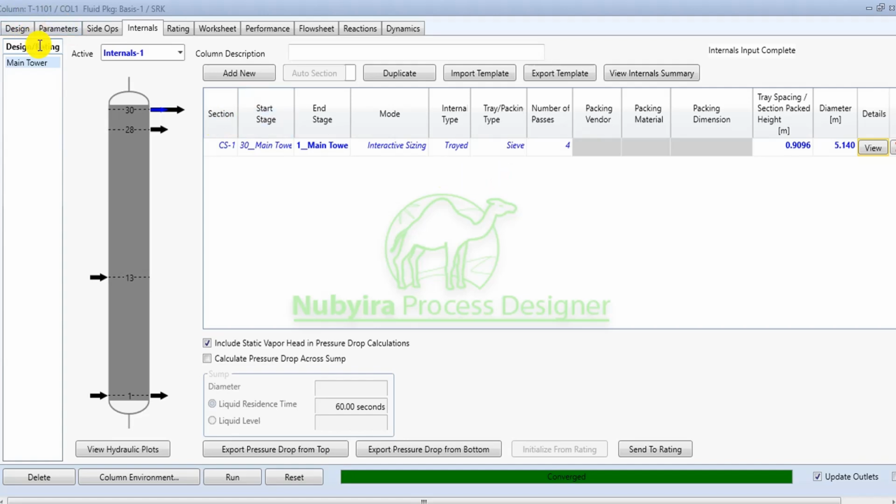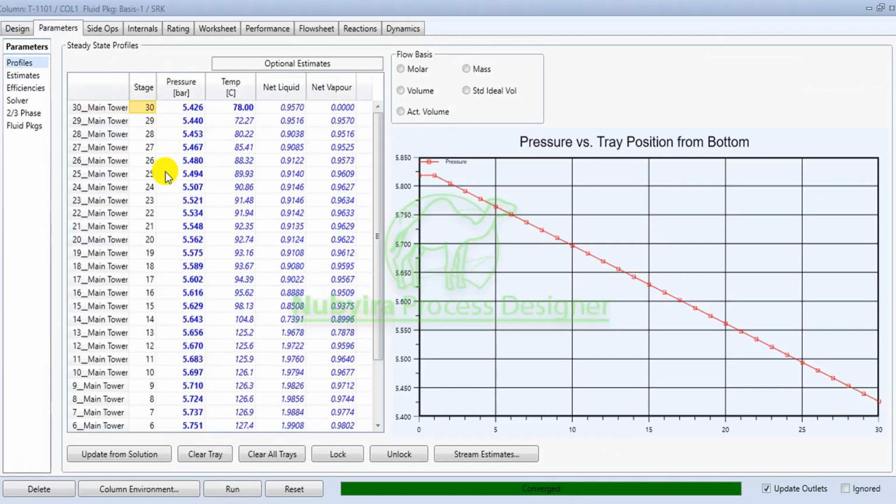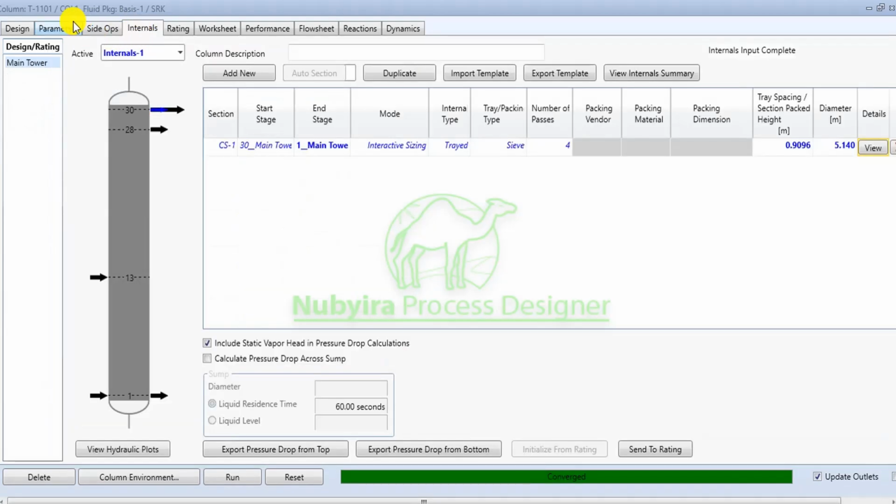So then you calculate, once you specify the pressure drop here, it will calculate the column material balance based on the standard MESH equations. Then you'll be able to get the result again, and the analysis will be done instantaneously with it. It gets integrated. Then you can check if you are seeing weeping again. You have to recalculate the column analysis again, you understand, so you get the right value for the pressure and the tray sizing analysis. So, and I'm going to do that now, but before I do that, I have to